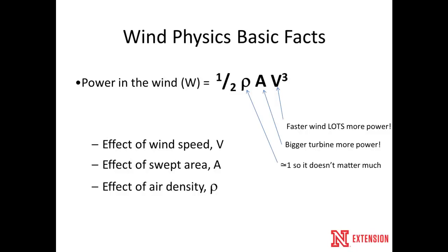So even if you have a windy city, like Chicago, inside the city limits, or really inside any of the areas where there's a lot of houses and other things, there's so much wind shear that if I want a turbine, I have to get it way up above all of those things. And if that's feasible, great. If it's not, don't put anything low to the ground, especially in urban areas.